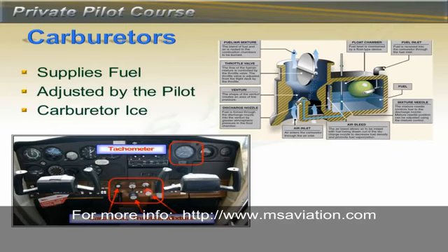If you remember from the aerodynamics presentation, a venturi creates an area of low pressure. This low pressure literally sucks the fuel out of this jet and puts it into the intake manifold. There is also a throttle valve shown at the top of the carburetor. This valve opens to allow more air to be pulled into the intake manifold, which in turn makes the venturi effect stronger, which sucks more fuel out of the little jet.